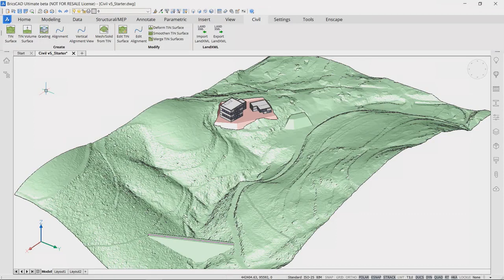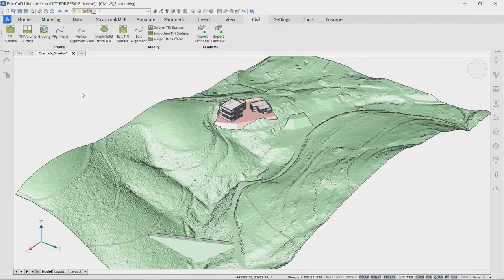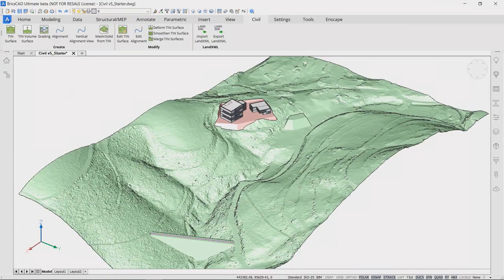So to design the road, we need alignments, because the road or other linear objects are twisted in space. They are twisted in horizontal and vertical direction. So you cannot just use simple polylines or any other known geometry in CAD. You have to use the proper geometry, and proper geometry means that you have straight segments, you have curves in horizontal and in vertical direction. You could also have spirals. We do not have spirals at the moment. We'll add them next year.